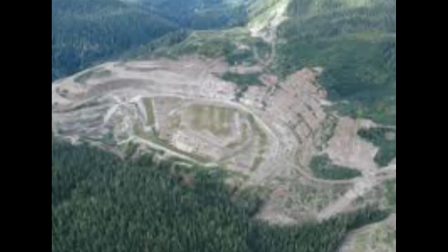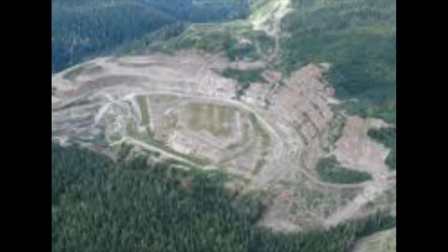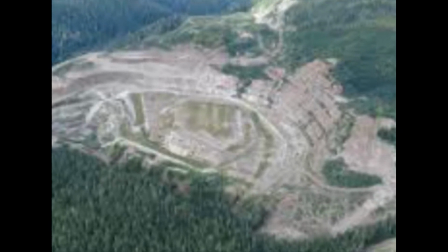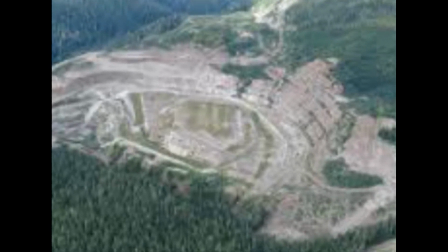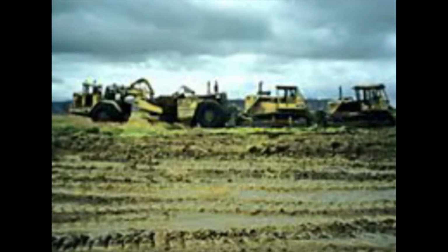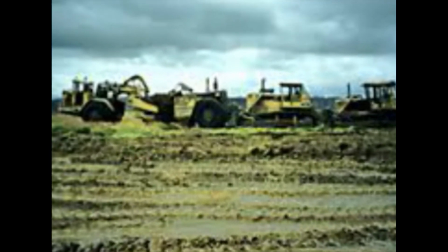Terrace mining is used where the overburden is too thick or the floor of the pit, that is the ore inclination, is too steeply dipping to allow waste dumping directly over the pit, as in the case with a dragline and strip mining. It is necessary to use intermediate cyclic or continuous transport, for example trucks or conveyors, to transport the overburden to where it can be tipped back into the previously mined void.